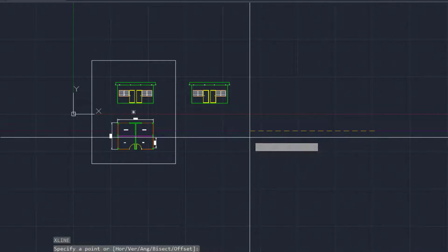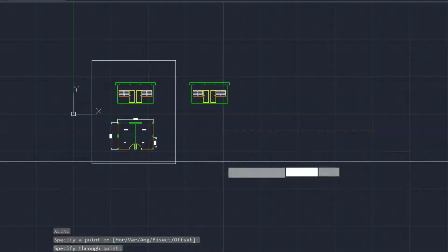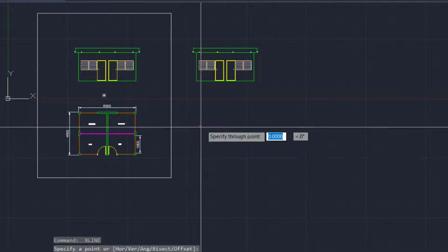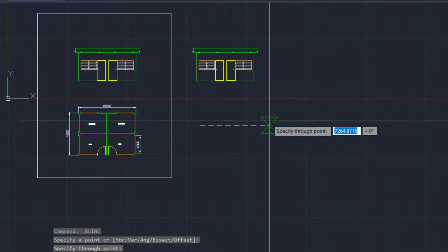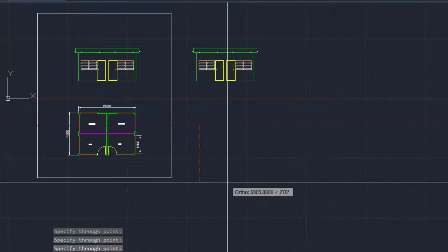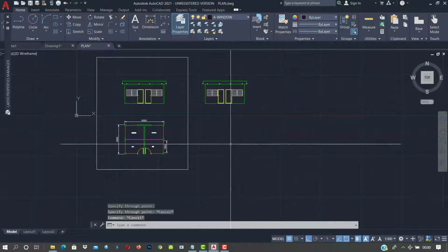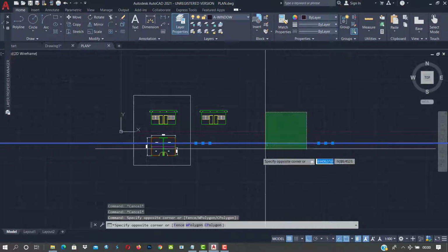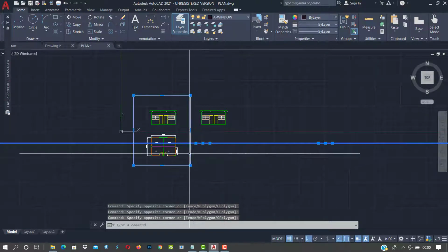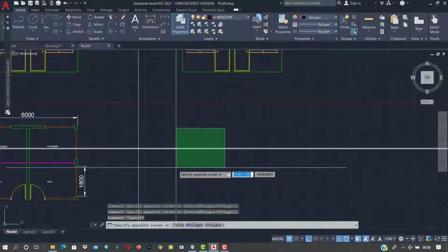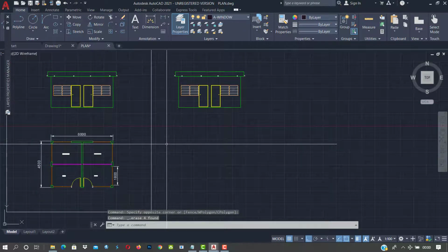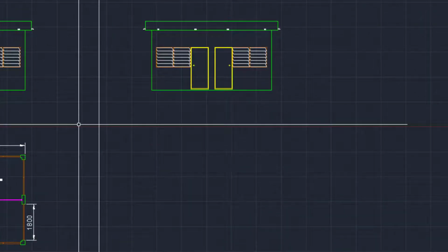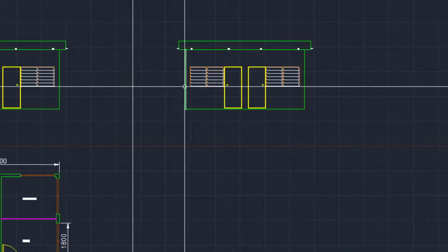It creates a line of infinite length. Let me create one so that you see. As you can see, it's not really visible, but you see it. I hope you can all see the line that I've drawn, because of the layer that I chose. So let me make the wall my current layer, so as to avoid any confusion.